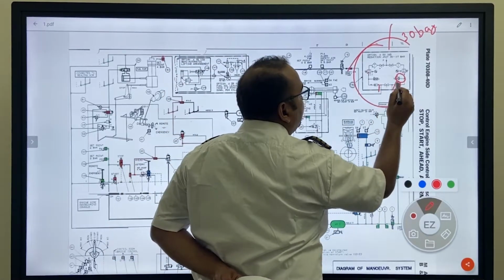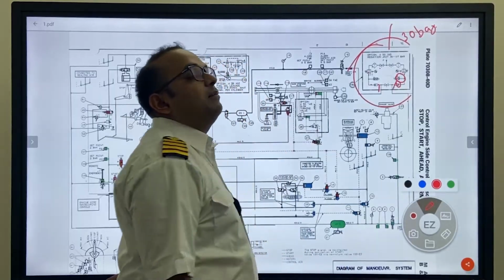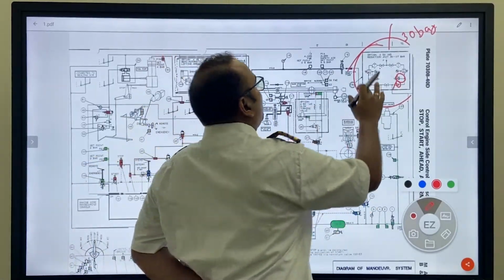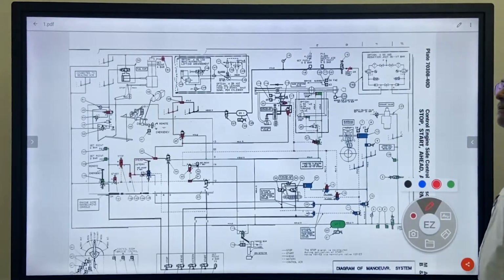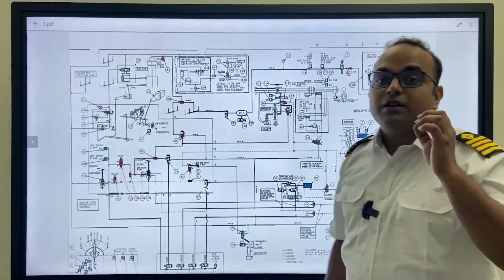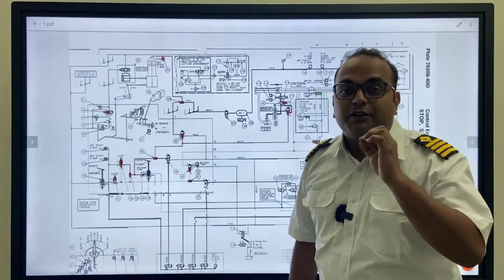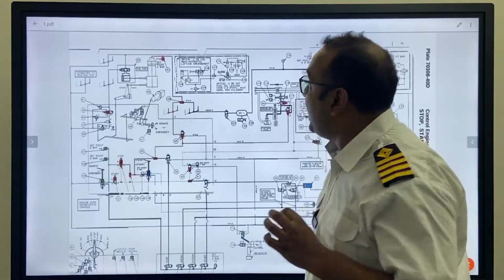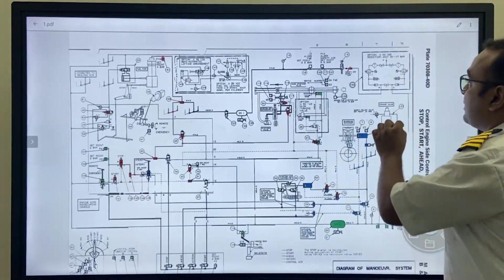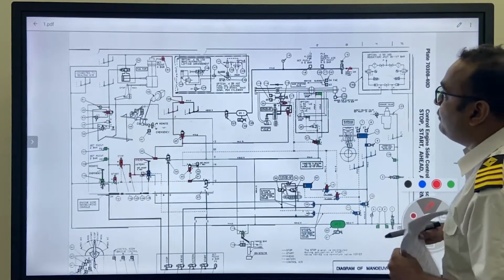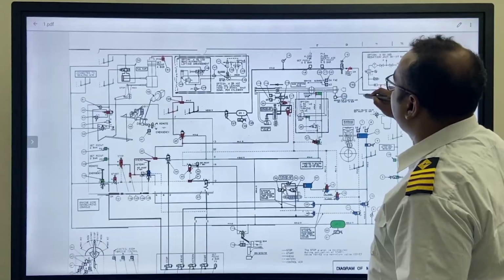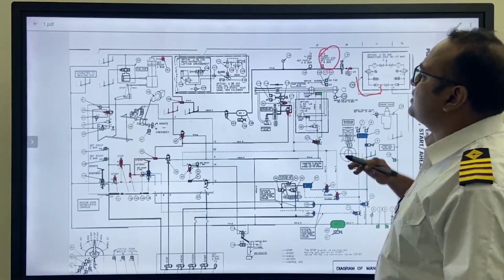It has reached to point B. This side reached to point A, and point A and point B are coming exactly from the same source of 30 bar. So now from 30 bar we have reduced the pressure to 7 bar. We have reduced it to 7 bar because this 7 bar is ideal for the control air, and for the safety side, for point B, we are keeping around 6 to 7 bar.